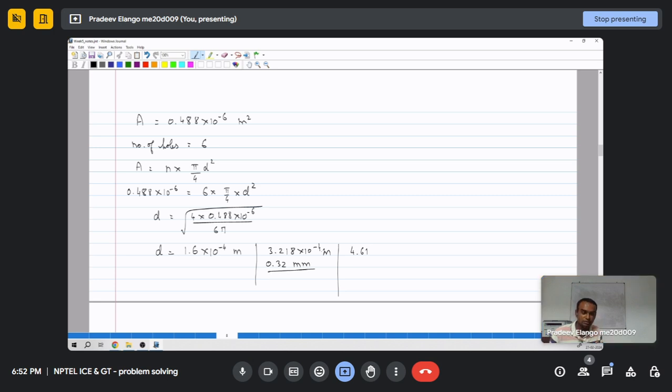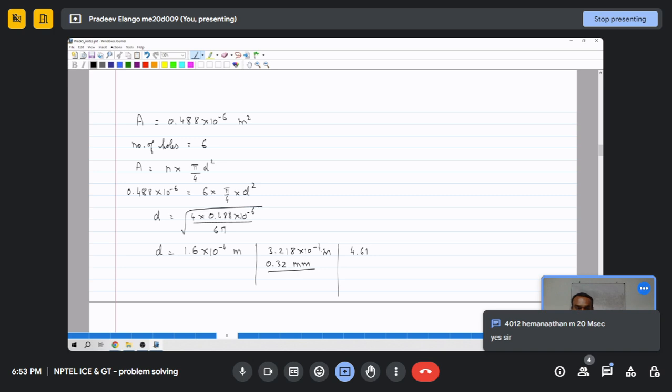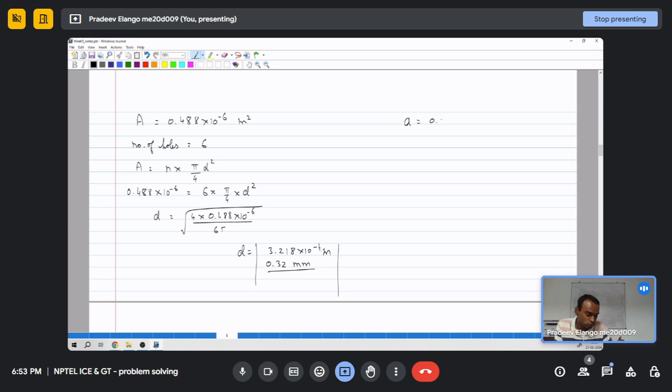Yeah. This is even bigger for a diesel engine. A modern common rail diesel engine will have a diameter of 0.14 mm or 0.17 mm in that range. So that means it's 140 micrometer. You can think of how small it will be. I think hair is 200 micron or something. At least in the order of the diameter of hair.